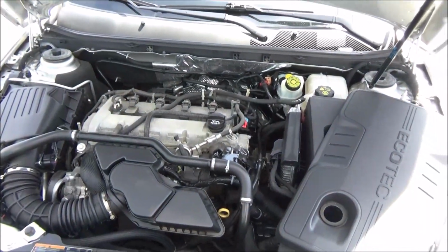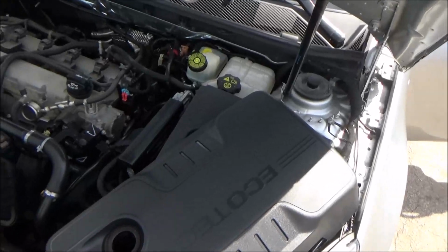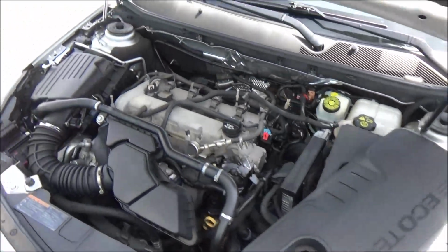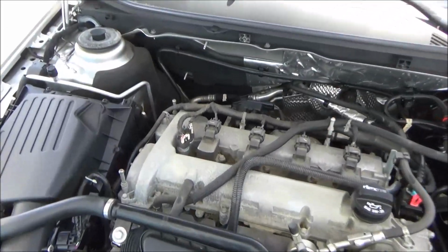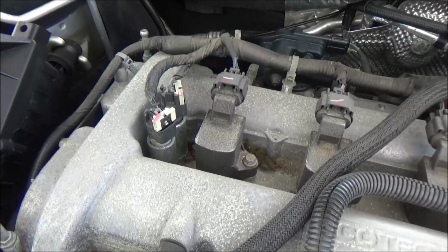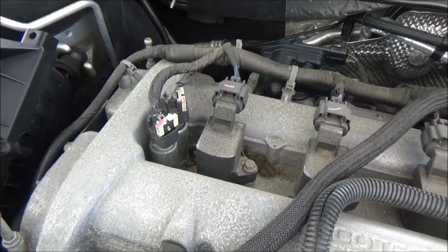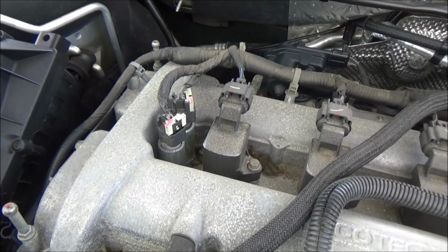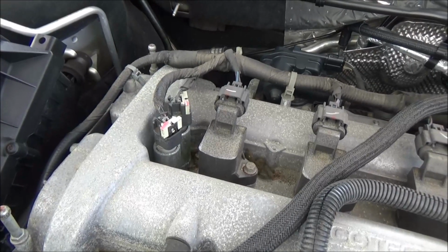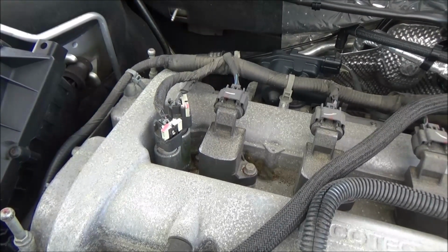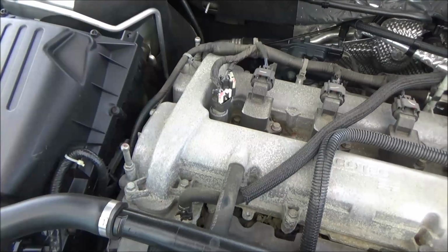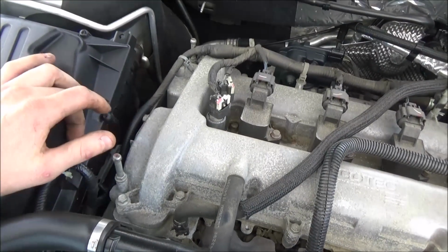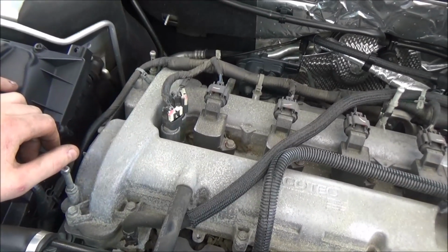All right, guys, this is the car we're working with. As you can see, I already had this engine cover off. And if we look on the top of this valve cover, these are our guys right here. These are our 2 intake and exhaust camshaft solenoids. The engine computer is going to energize and de-energize these in order to move the camshaft actuators, which are going to be attached to the cam gear inside of this valve cover.